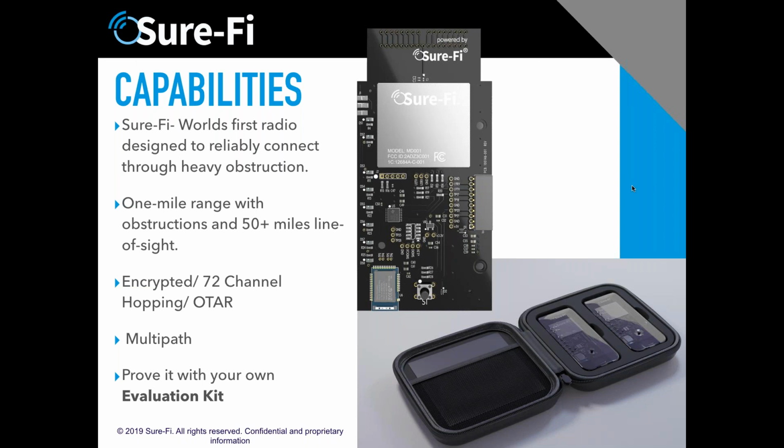You're talking about RF interference when using multiple SureFi units together. This has been something that's great about this product: it comes paired from the factory, so it's only talking to its partner. Last I heard, we used about 70 units in a single application lined up next to each other, and there's no interference. That's because it has 72 channels of hopping plus rekeying, so it gives you many options, and those never interfere with each other. We've been very fortunate with that, and of course we tested and worked that out ahead of time. So no interference when using many SureFi units.